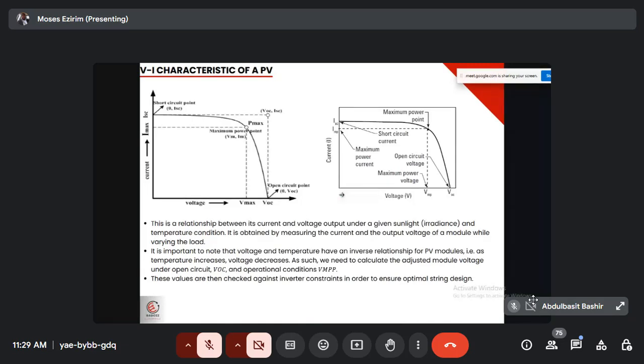That's the reason why for C&I, once you've done your installation, we do commissioning. During commissioning, you apply the loads to it. You see the behavior of all these parameters. You see whether it applies to your design, because you must have done your design before you do your installation. And during commissioning, you now see if the installation is actually playing out what you designed before you are good to go. All right, now this is important.